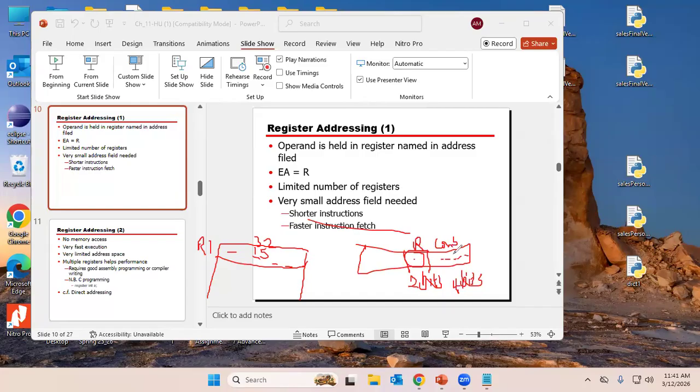And then, when the instruction is smaller in size, it takes less time to fetch it into the CPU to execute it. And when I have 2 bits here, I have up to 4 registers. If I have 4 bits here, I have 16 registers. We'll talk about it next chapter. 16 registers, and this is lots of registers to work with inside my CPU. So this is a limited number of registers, depending on the number of bits available. If 2 bits are available for this register field, then we go to 4 registers maximum: 00, 01, 10, 11. If they are 3 bits, 8, and 4 bits, 16, and so forth. Done, I said what I had to say.